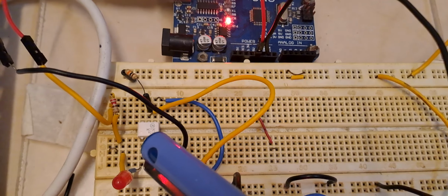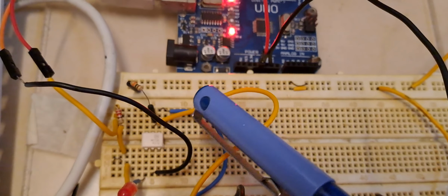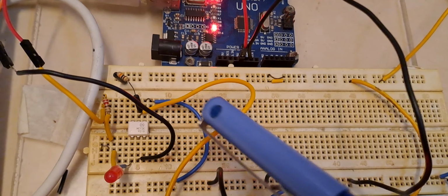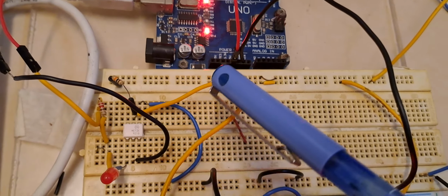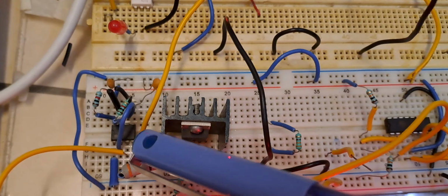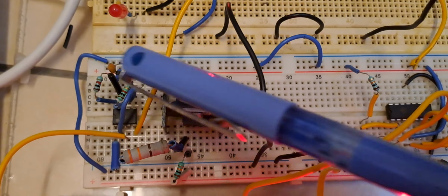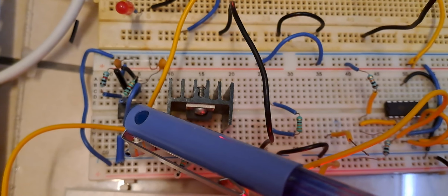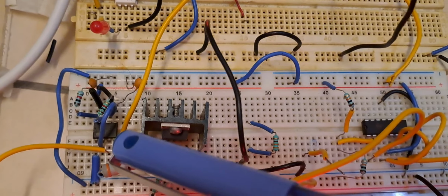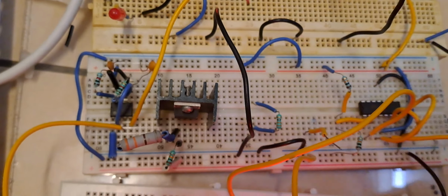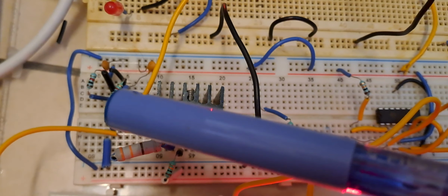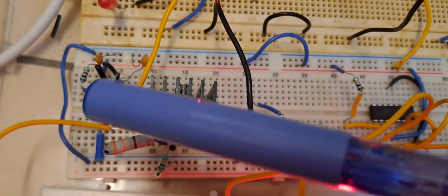So the output of the optocoupler, here you can see this yellow wire, is the same data waveform, but it is isolated. So basically this is the isolated data waveform, and this data waveform is fed to this modulating circuit. This circuit is going to modulate the data signal with the carrier signal. So you can see the data is coming and it is received by pin number 4 of the 555 timer IC. You can see, the 555 timer IC is wired as astable multivibrator mode as an oscillator.